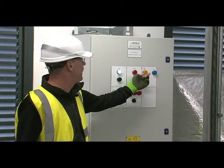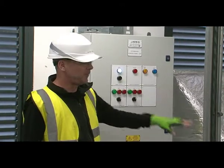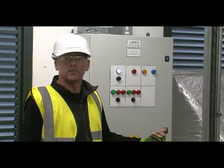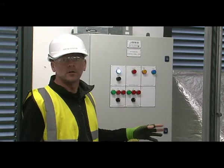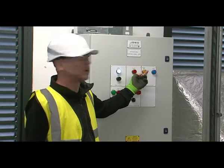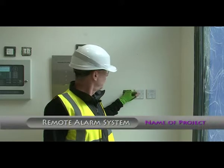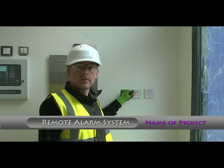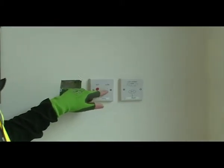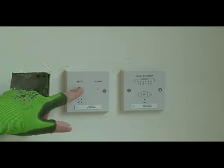Adjacent to this we have a warning lamp, not a fault lamp, for the filter dirty. There's a filter in the supply unit that will get clogged with dirt and dust that comes in from the outside air. As that gets dirtier, it will eventually create a lamp here indicating that the filters will need to be changed or cleaned. We have a remote alarm unit which will indicate with a visual and an audible alarm that the BMS system has logged an alarm. This will always be on whilst the alarm is active, but it can be muted by pressing the mute button.